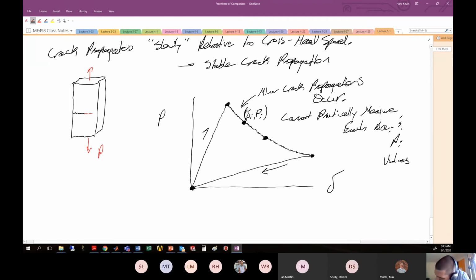All right, later on down the line here, we have another value, which is delta J and PJ, right? So let's say I have these two points on this load displacement curve, and I happen to know what the crack length is at each one of those individual locations. So let's say I know at delta I, comma, PI, that crack length is AI.